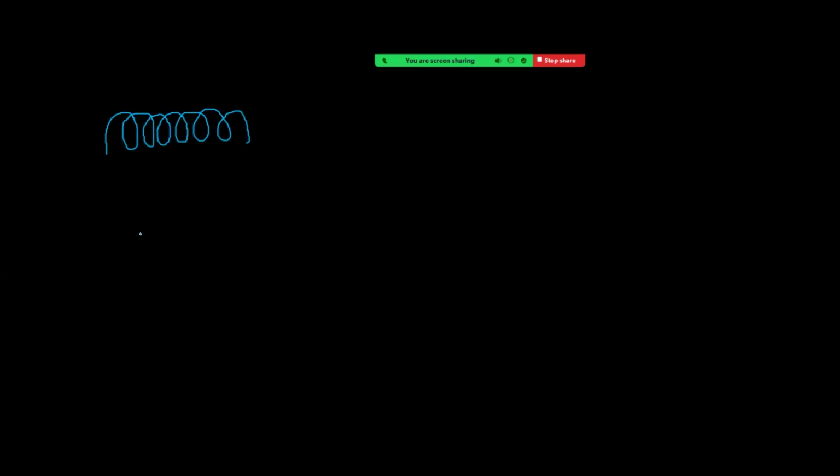Now see what I am writing here. First we have to focus on flux, which is equal to L into I. So first we have to find the flux linked with this solenoid. After having the flux, divide that by the current flowing in it. That gives the coefficient of self-induction. Okay.